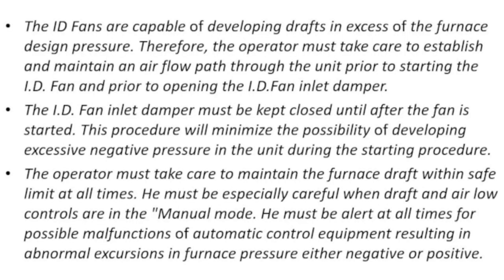The ID fans are capable of developing drafts in excess of the furnace design pressure. Therefore, the operator must take care to establish and maintain an airflow path through the unit prior to starting the ID fan and prior to opening the ID fan inlet damper. The ID fan inlet damper must be kept closed until after the fan is started. This procedure will minimize the possibility of developing excessive negative pressure in the unit during the starting procedure.